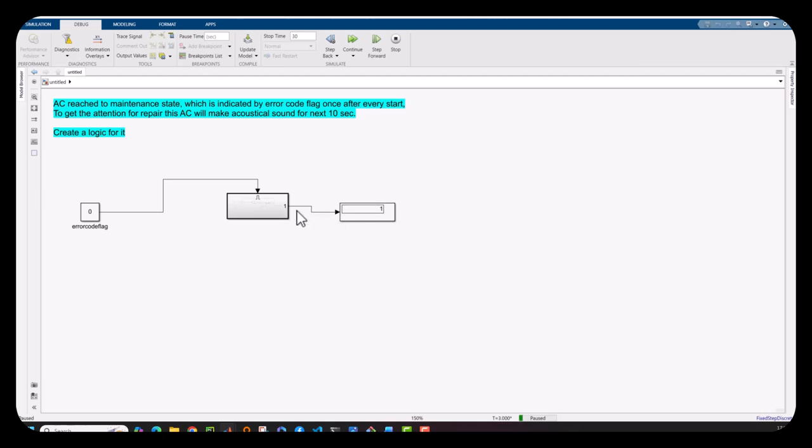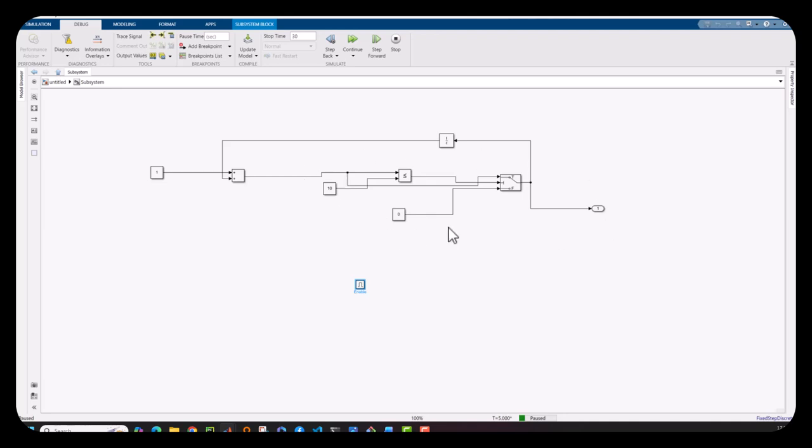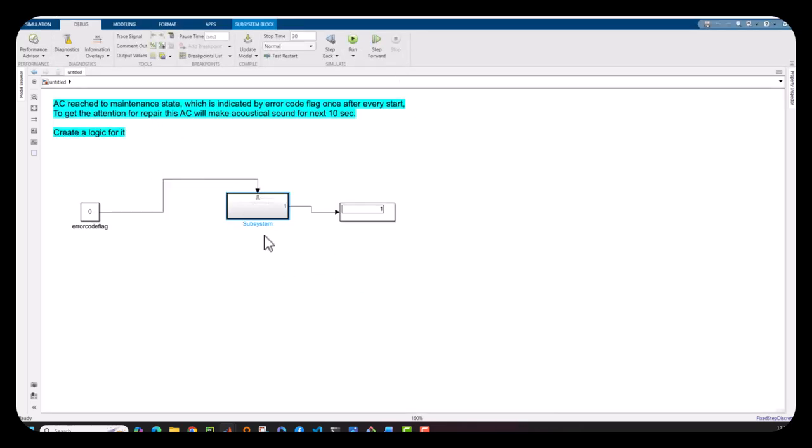So then this timer should continue, but here if we see, the timer holds the last value because this enable has gone. So this subsystem is no more enabled now, and that's why it is only holding the last value as per the held setting. Right? So this enable logic will not work for our requirement.